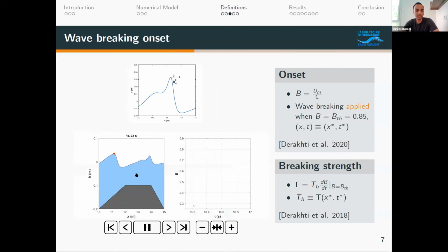Exactly. If I identify this crest, at the peak point I calculate the wave celerity that was locally defined by the previous formula, and then I track this in time. I look at the next time step, see where the crest is, calculate it again, and follow this through. The Hilbert transform is from X to X.